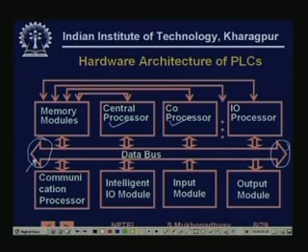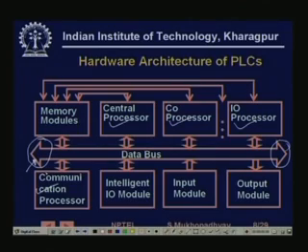So, you have a central processor, various kinds of co-processors, I/O processor. Nowadays we are in the age of embedded processors, so some of these processors even use DSPs. So there could be numeric co-processors or I/O processors. Generally there are communication processors for specific communication to kinds of devices like operator stations, or for communication on the network. There are various kinds of I/O modules.